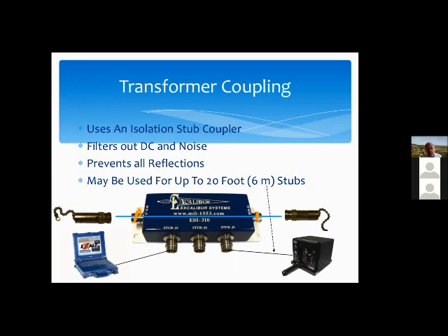So what I'm going to do is run a wire from here to the other side of the lab. On that side, I'm going to stick it into a coupler just like this. And then that coupler is going to have an output for the bus controller and a second output for the RT that's on the other side of the lab. So now I've got 1 wire connecting this coupler to that coupler, and I've got 5 boxes attached.